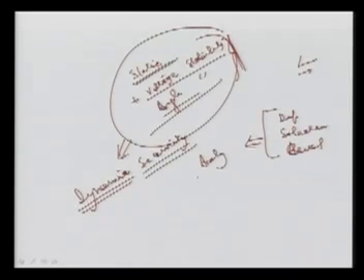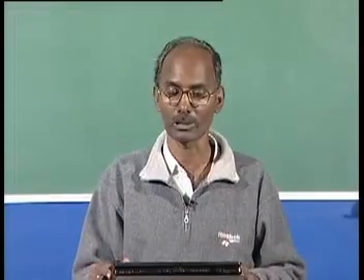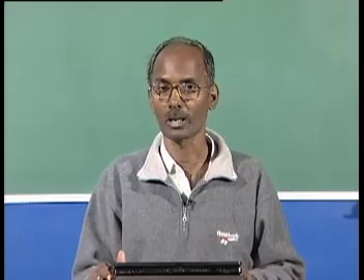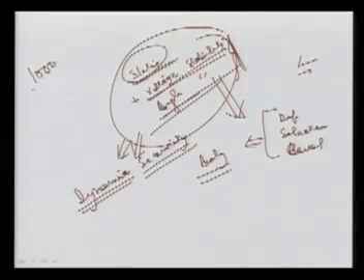And if you include the power system dynamics along with the voltage stability limits and angle stability limits along with your static security limits, then we can achieve dynamic security, and that can be a further research topic. A lot of research is already being done, but we still require a very fast and accurate method for this, because in the power system, as I said, there are more than 1,000 contingencies.